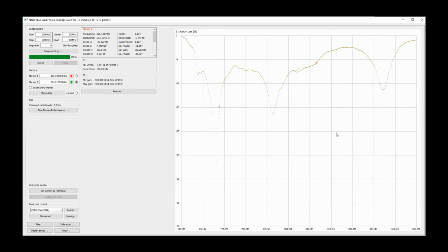Where was the button that lets you add a marker? You go to display setup, and then at the very bottom where it says markers, you can add or remove. Yes, so that the pop-up is not showing up on the stream. Right. Yeah. If you hit display setup, another menu comes up, and at the very bottom of that, you can add or remove markers. I knew it was on there somewhere. I'd done it before.